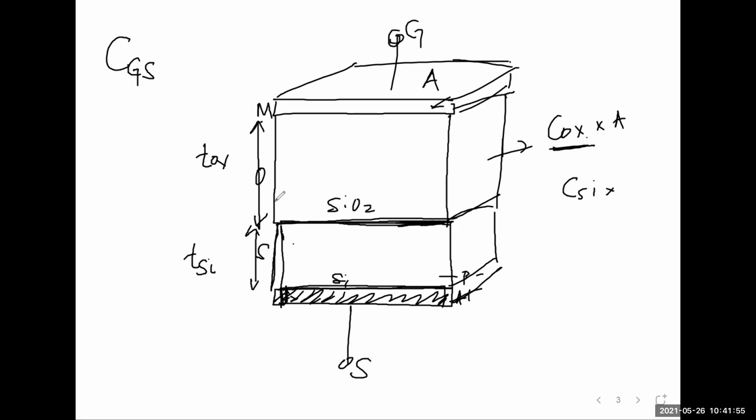And do you remember what happens if I put a voltage? So if I put a positive voltage V here with respect to this node S, what happens? You'll have positive charges come here. And because this is silicon dioxide, obviously the electric fields will go and they'll start kicking away some of the holes, because the majority carrier is holes.